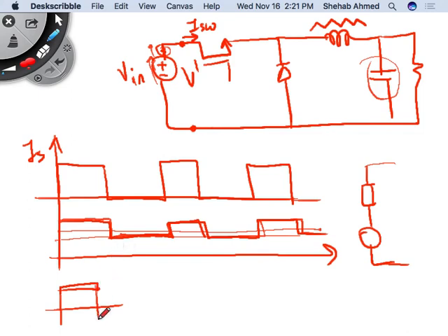It's a different voltage. It's not. This was V input minus V output. It's now V input plus a drop minus V output. Right? So here it was minus V output. Minus V output part will not change. But this changed. So for the same duty cycle, the area on top will not equal the area on the bottom anymore.